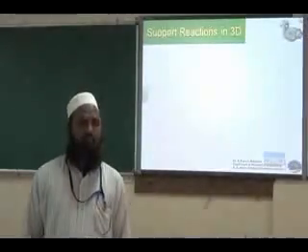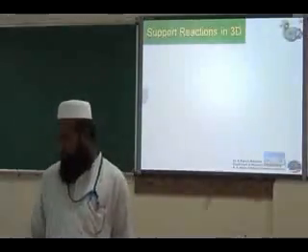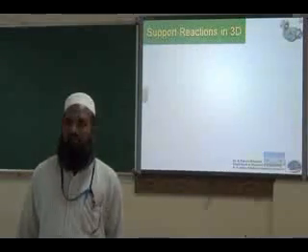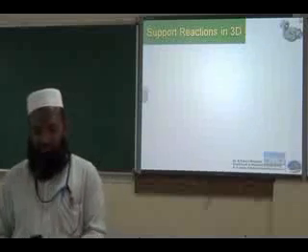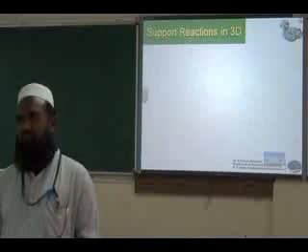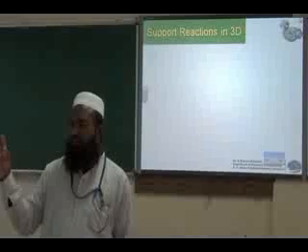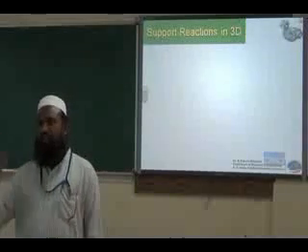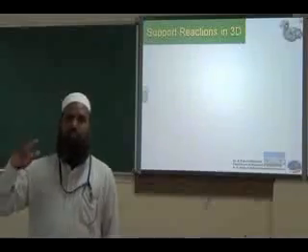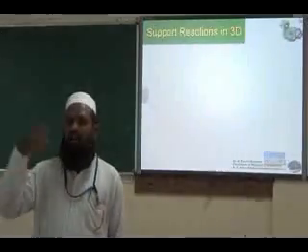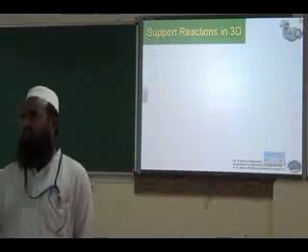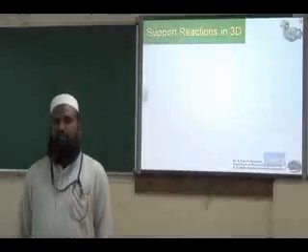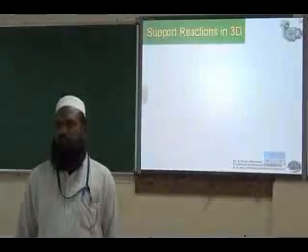Along X, along Y, along Z, along XY, along YZ, along ZX. No. Okay, half is correct. Actually, this is 3 forces. You will have three translations along X, along Y, along Z. And the next 3 are rotations. So you must say around X, around Y, around Z, or about X, about Y, about Z. So 3 translations and 3 rotations. So you will have 6 degrees of freedom.